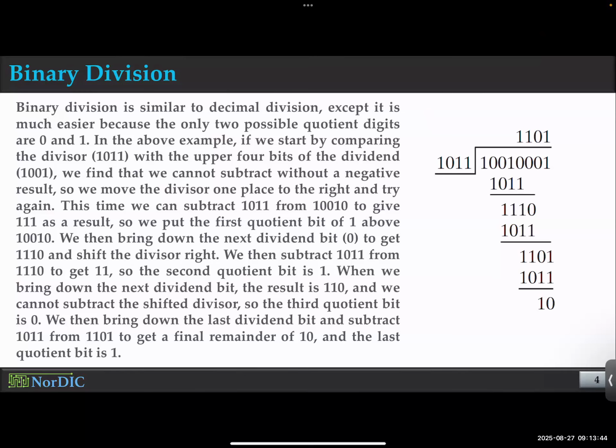Apparently division in binary is easier than division in decimal. Here is why. When you try to divide a number in decimal system, say 37 by 7, there are so many sevens that could fit within 37, as you can imagine. But for binary, there are just two options, 0 or 1. That means a number will either fit within another number or it will not. So all you have to do is check whether the number that you are dividing with is bigger or smaller than the one that you are dividing. Let me show you one example here.